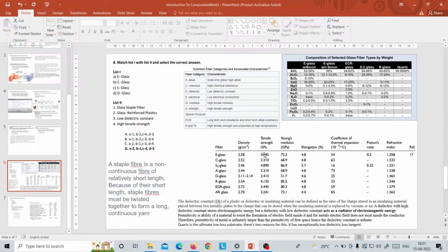So in case of tensile strength, you can see this is the column for comparison. In this, the glass fiber which will have highest tensile strength, you'll try to use that one. Fine. So it's 4.8, which is S2 class. So this you'll be using. If cost is not at all your factor, then you'll simply go for the strength of individual reinforcement materials and directly use those for making the composite. Fine. If cost is an issue, then you'll have to do an economical analysis.